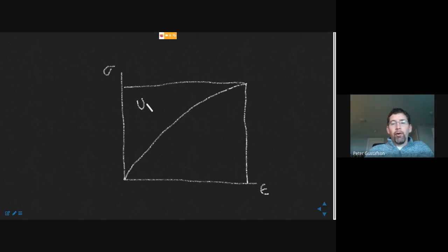So we call this U0C, the complementary energy, and we call this U0, the strain energy. Now the key here is if this is elastic, the recoverability of either one of these energies is dependent on this being an elastic problem. What does that mean? That means if I load up this curve and unload, I come back down the same path.